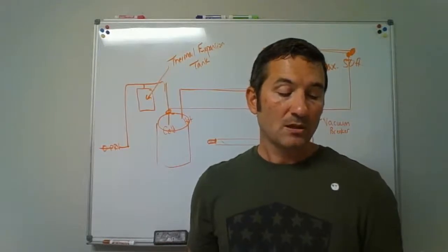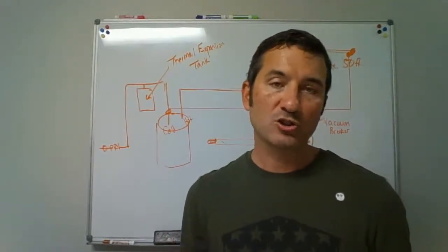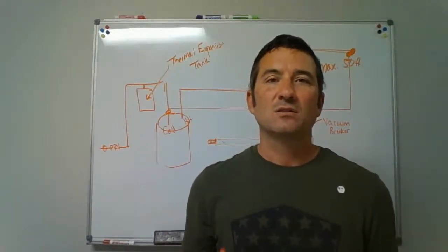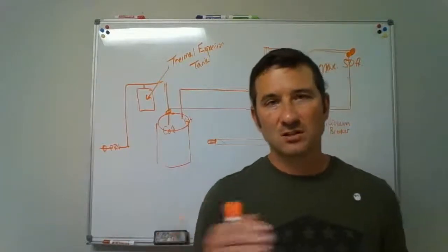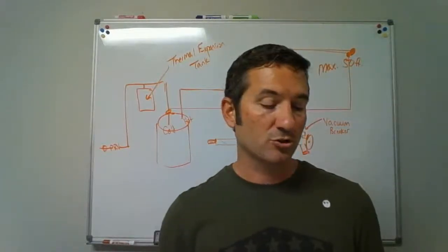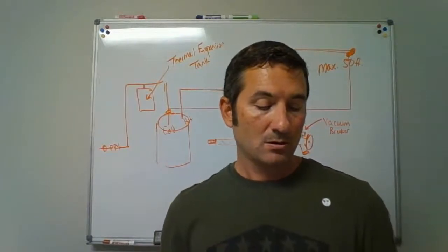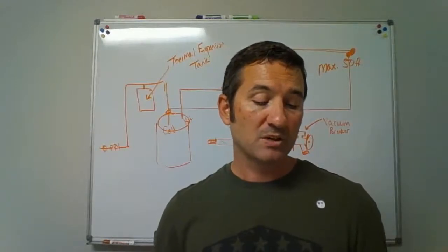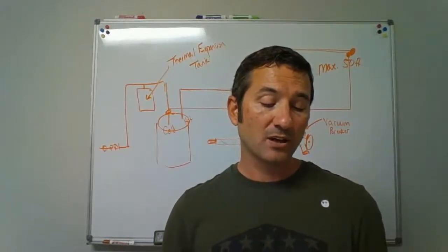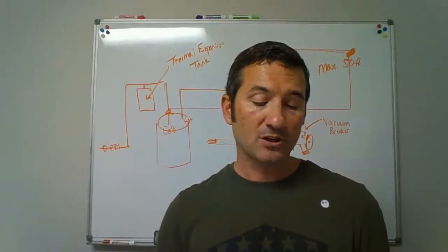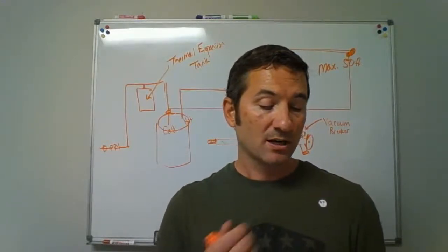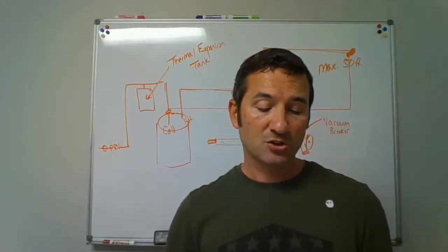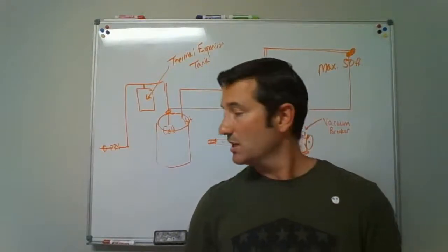Question 11. The whole house shutoff in a crawl space needs to be within 3 foot of the crawl space door. That shutoff valve in a crawl space is going to be within 3 foot of the crawl space door. Is that true or false? Question 12. A vacuum breaker must be installed 6 inches above the flood level rim of the fixture or device. Is that true or false?